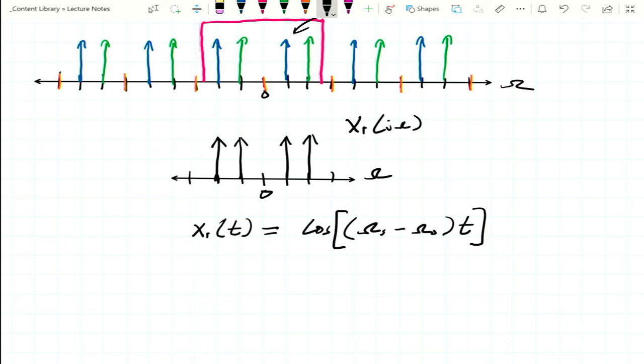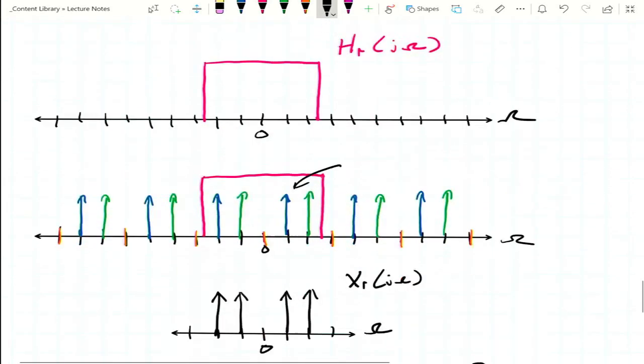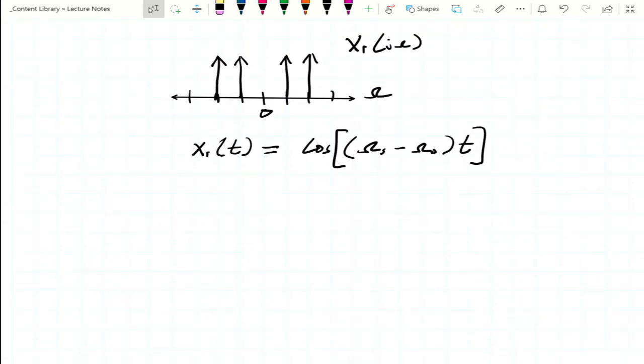So that was a long roundabout way of saying that when you're taking your samples, your sampling frequency has to be greater than or equal to twice the largest frequency present in our signal. Any questions about that?